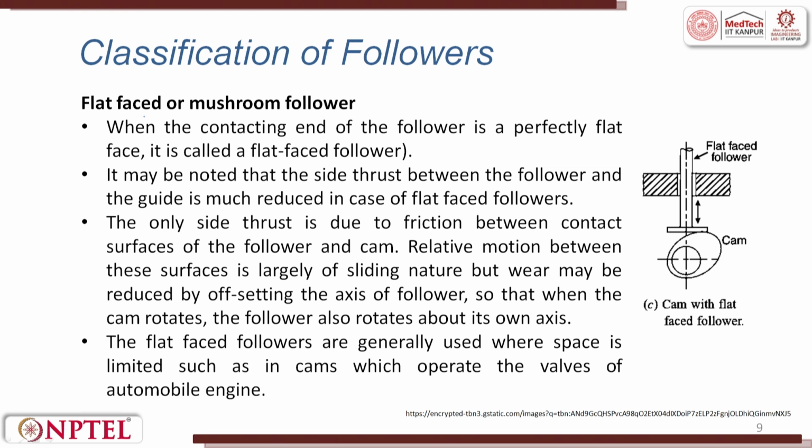Then the flat shaped or mushroom follower. This is a flat type follower. When the contacting end of the follower is a perfectly flat face, it is called a flat faced follower. It may be noted that the side thrust between the follower and the guide is much reduced in the case of a flat faced follower. This is the biggest advantage.